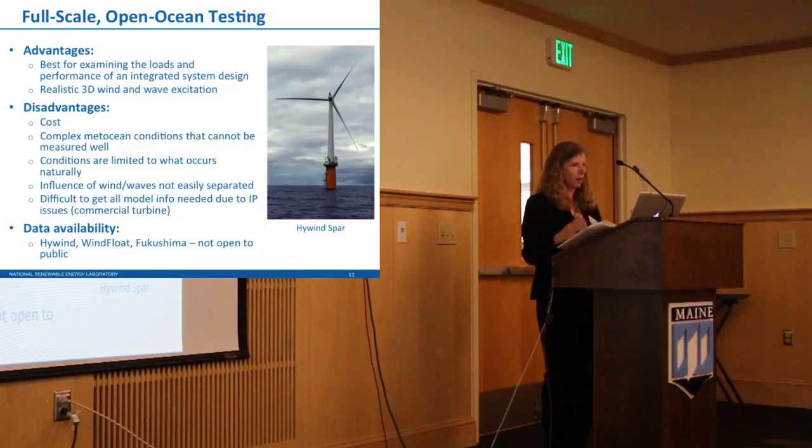Okay, so another approach to obtaining data for validation is to look at the full system in the open ocean. The advantage of this is that it's best for examining the loads and performance at an integrated system level. You have realistic wind and waves. We have the tank with these simplistic wind and waves, but in the open ocean it's all of a sudden very different, with this whole 3D wind and wave excitation that's very complex.